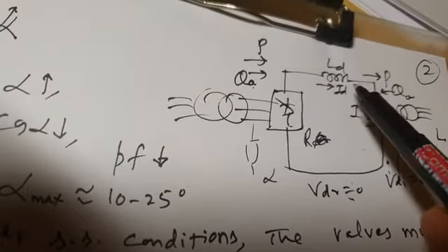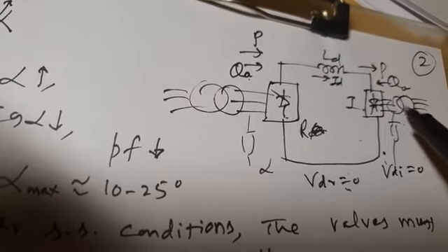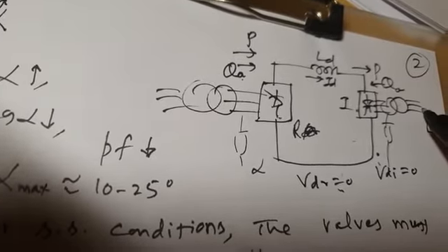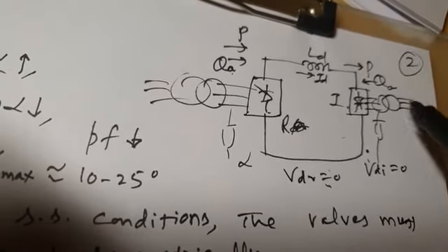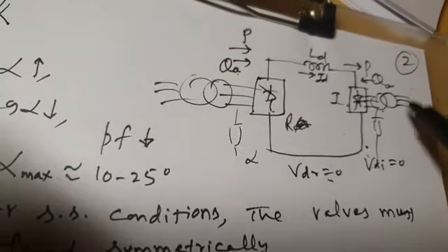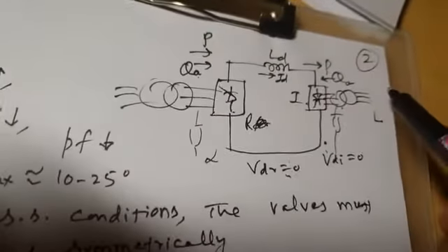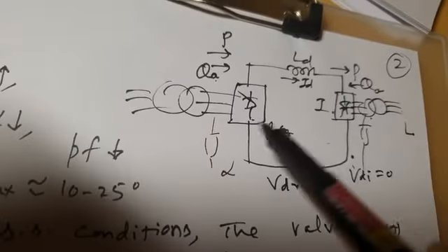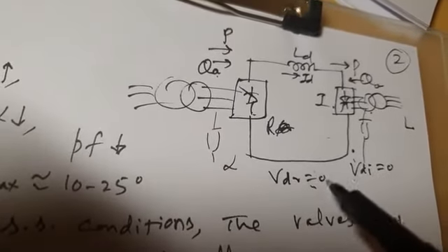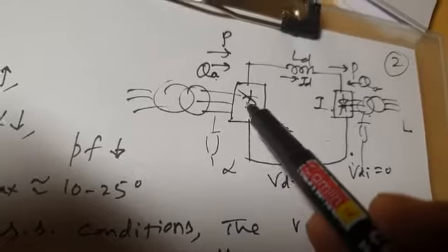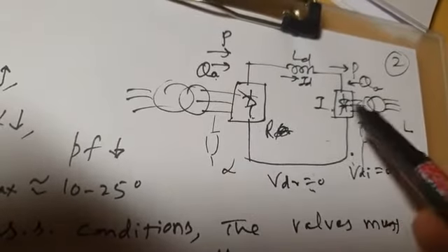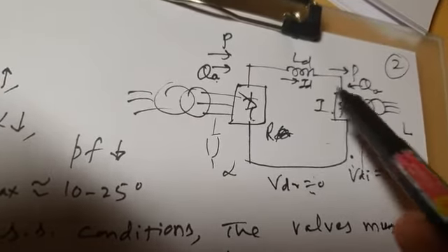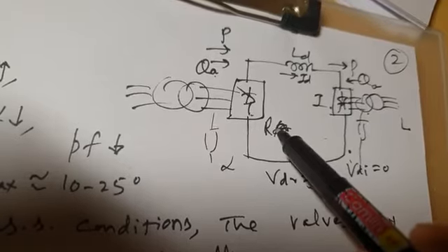And when the inverter side AC voltage is restored after a certain drop or dip, then normal operation will occur. So during abnormal conditions like an inverter side AC voltage dip, the controller has to act very quickly. It has to exercise the delay angle control in such a way that the rectifier side voltage also becomes 0.